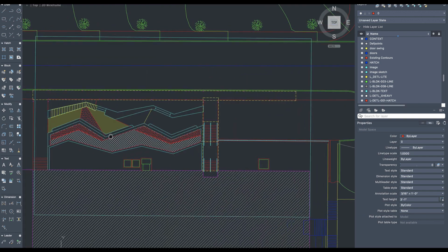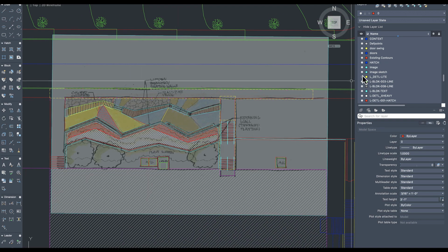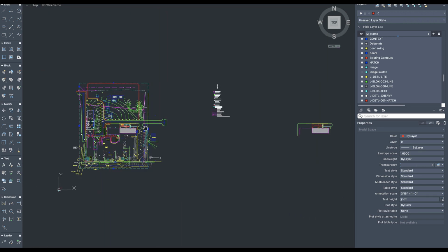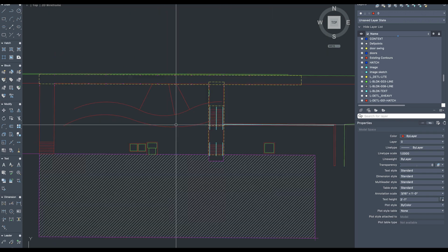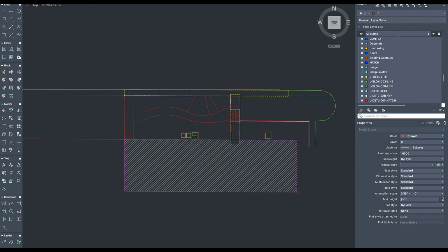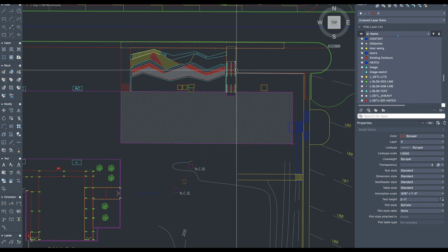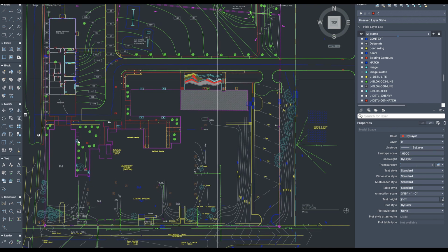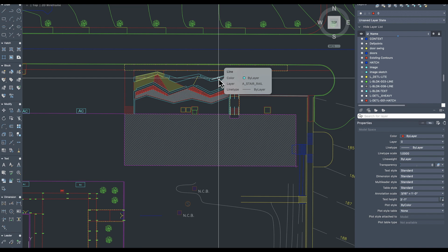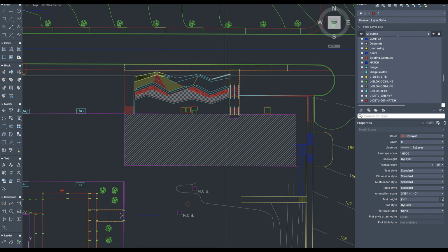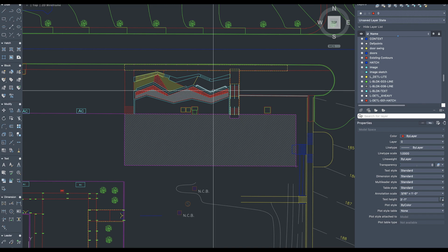We're not just blindly tracing it, but we're sort of advancing it, trying to get it more refined and precise through this process, whether it's one that's got curves in it, whether it's one that is just an irregular one, or whether we're just turning on ortho and doing a rectilinear design. Whatever the case is, you want to use guidelines that are going to help you focus in and do some line work that is, like I said, precise, known offsets, and something that's a little more rigid, a little more buildable, using whole numbers, not these sort of arbitrary offsets.